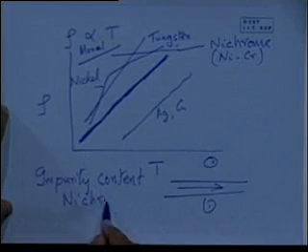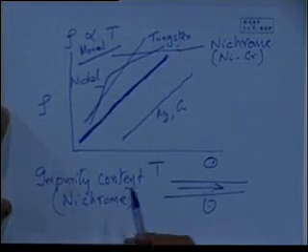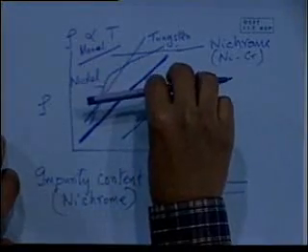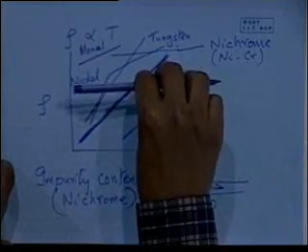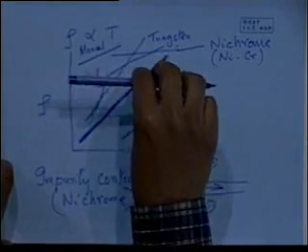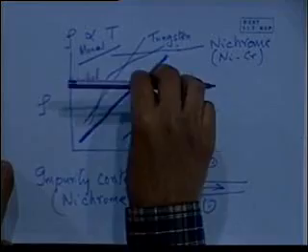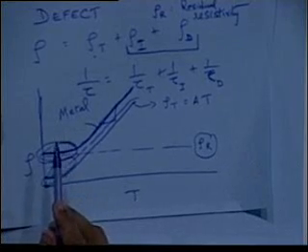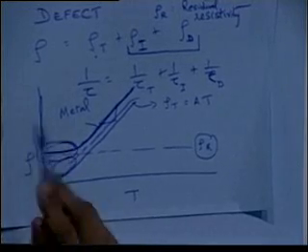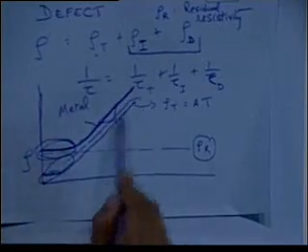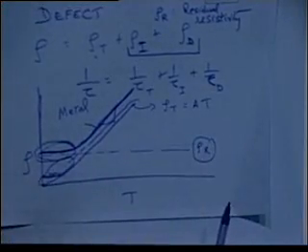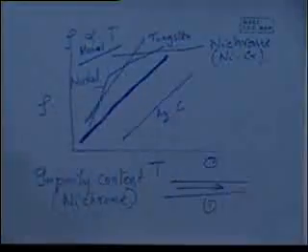Remember, for nichrome, we saw that the temperature dependence is not there for the impurity-dependent residual term. But let's say throughout the alloy, the impurity part dominates. There's so much scattering coming due to impurity or defect. Then we will expect that it will follow more or less a flat profile. And that's what we see in the case of nichrome.